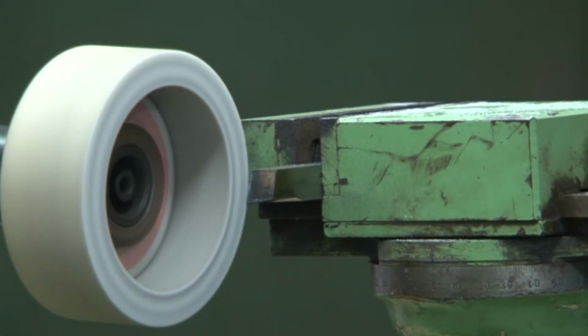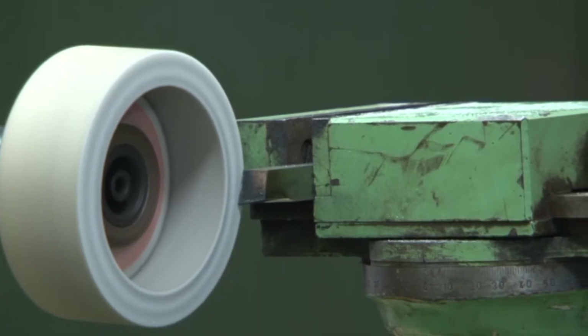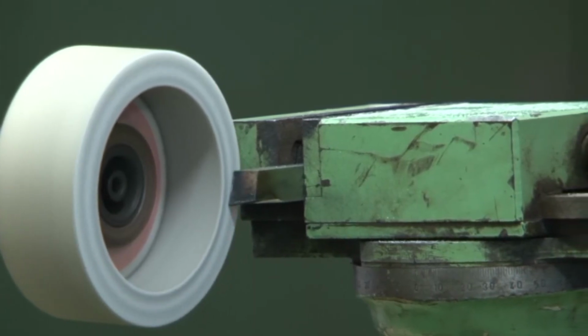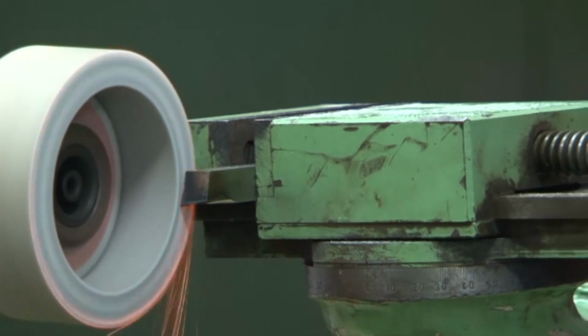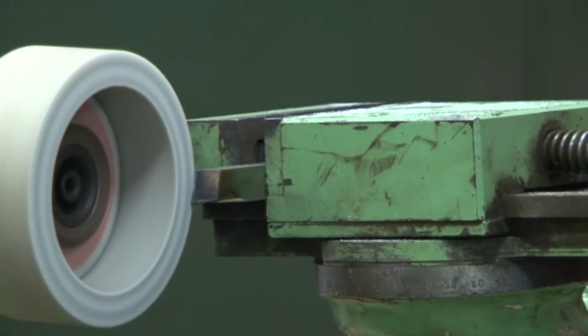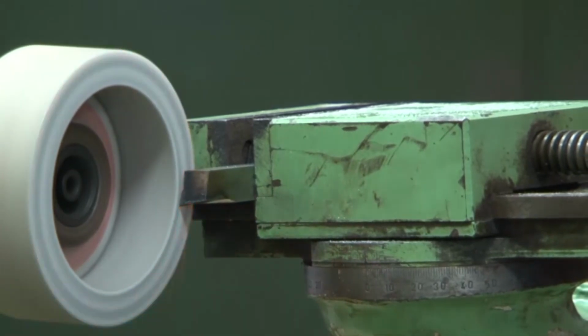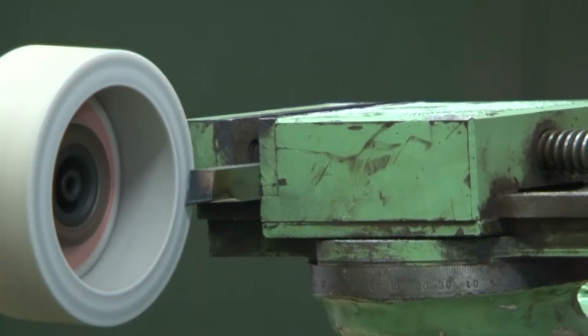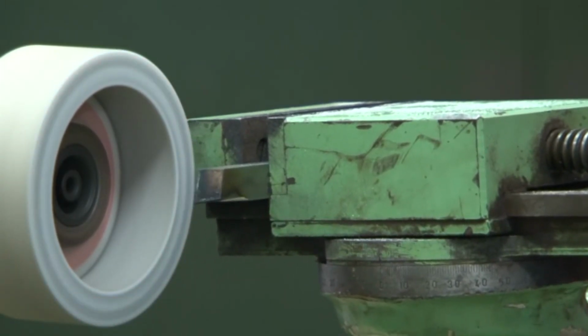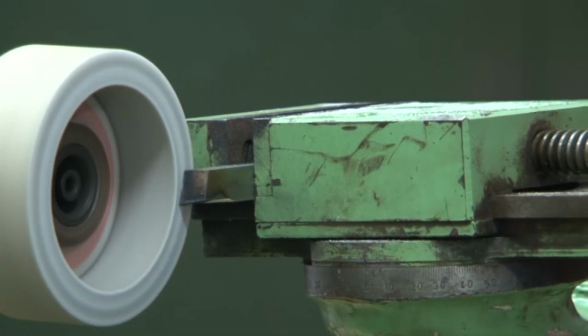See, in this case the setting of the tool is very important, how you are going to set the tool, so that the grinding process can be performed to get that particular rake angle. If you incline the tool, the rake angle which will be ground will be distorted. It will not be the same rake angle as you have initially selected.